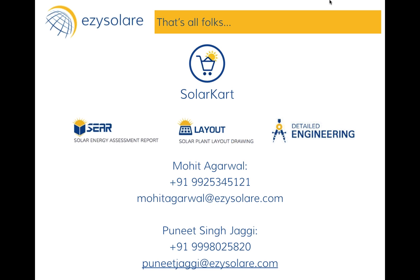Can we measure all the losses that are quantified in an energy assessment report, and how so? This is a question by Mr. Ketan. Not all the losses can be measured. The measurement can be at the parameter level, which is the radiation loss. Second is at the string level. The third is at the inverter level, and the fourth is at the transformer.